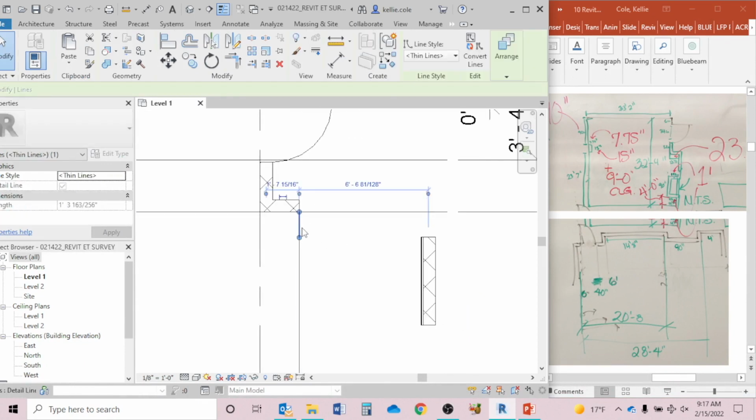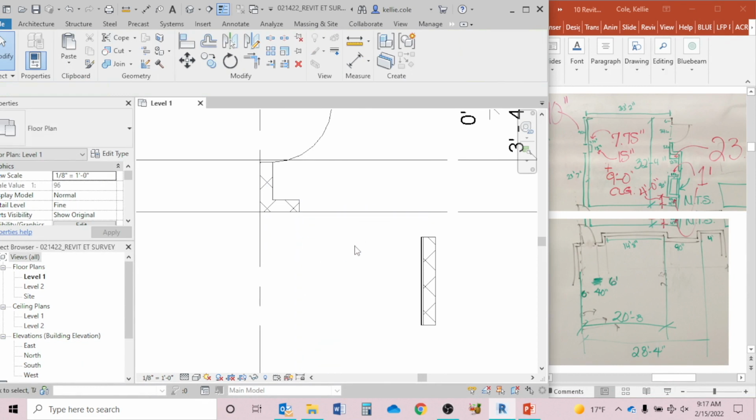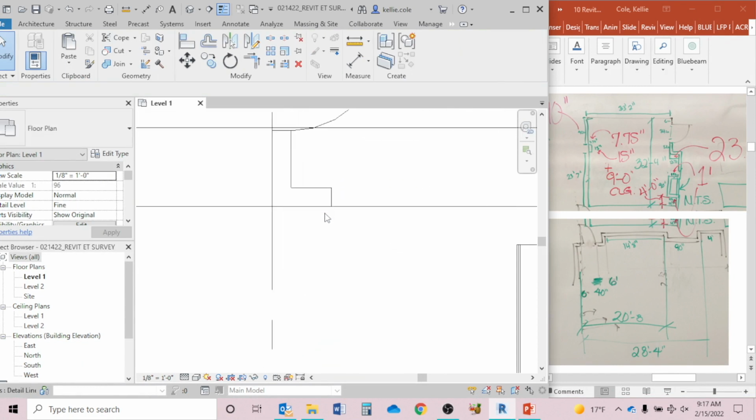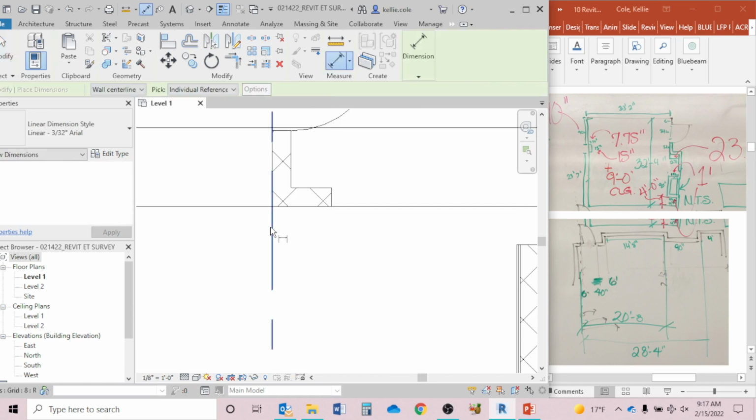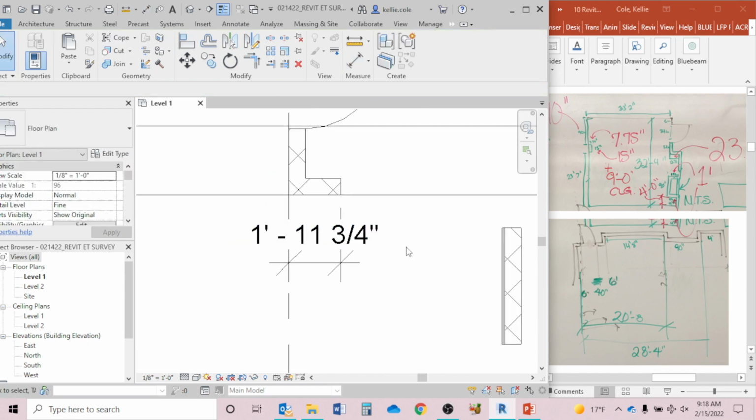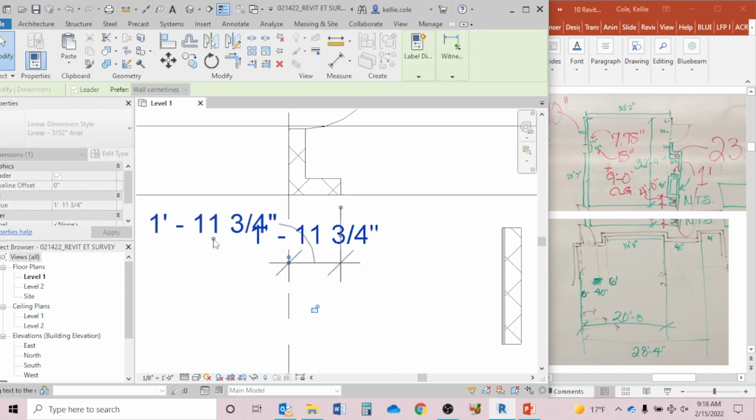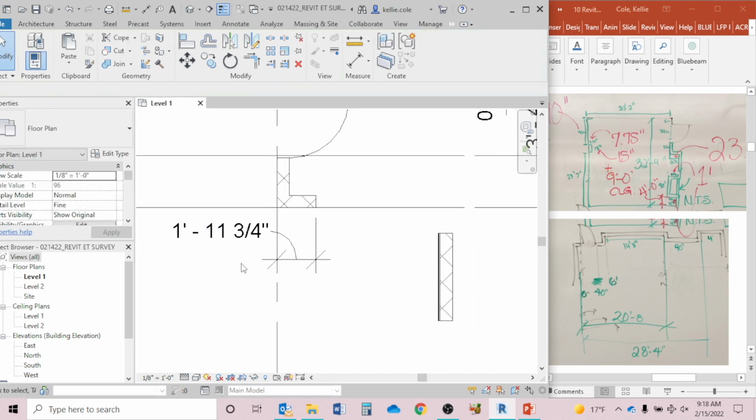If I didn't use my detail lines vertically, and I have DI dimensioned, that is 23 3/4, right? Or 23.75 inches. Okay, yes. I know that wall needs to remain that length. So I can align AL, end of that wall, to the front of this wall. I can trim TR.